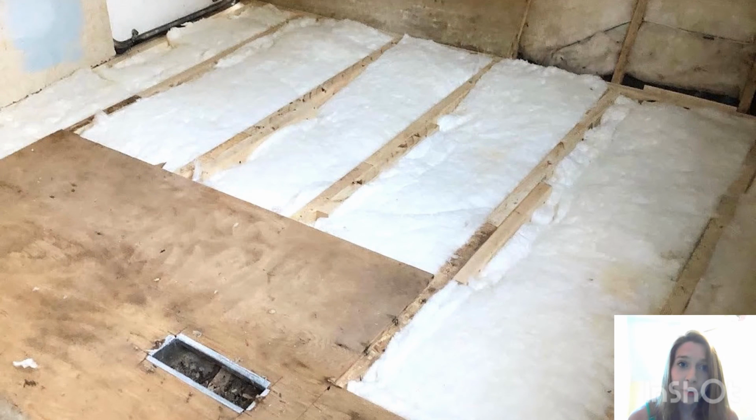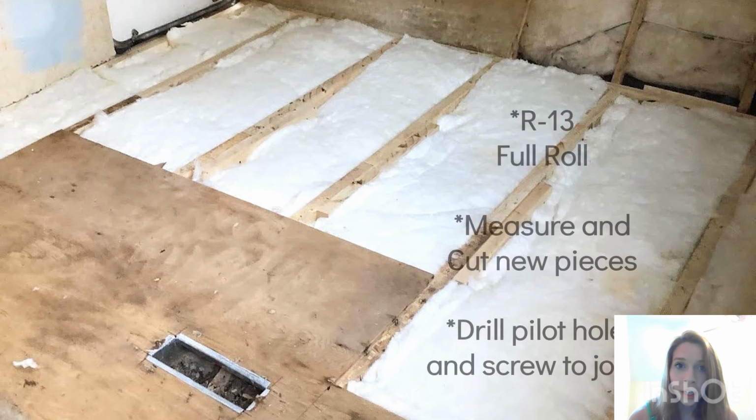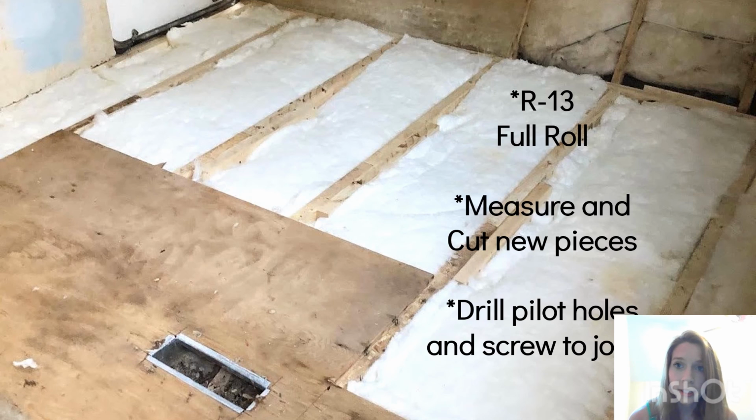Now, after your framing is complete and repaired, you will add a full roll of R13 insulation. You basically just measure and cut your new piece of subfloor after that and install using pilot holes and deck screws. I do not use construction adhesive on flooring, but you're more than welcome to if that's what you want to do.